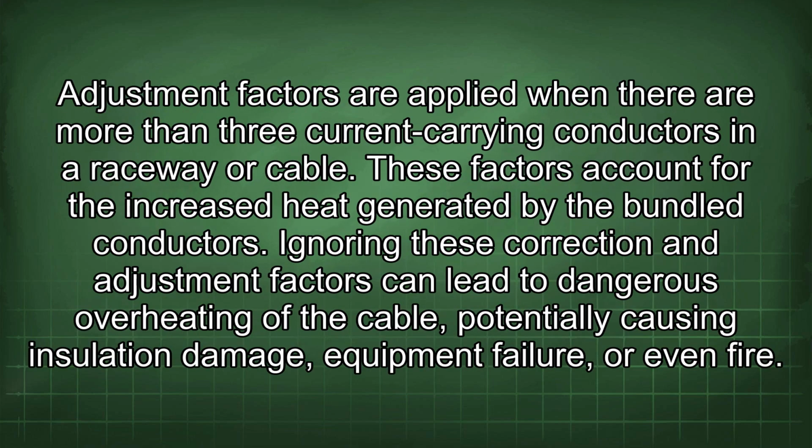Adjustment factors are applied when there are more than 3 current-carrying conductors in a raceway or cable. These factors account for the increased heat generated by the bundled conductors. Ignoring these correction and adjustment factors can lead to dangerous overheating of the cable, potentially causing insulation damage, equipment failure, or even fire.